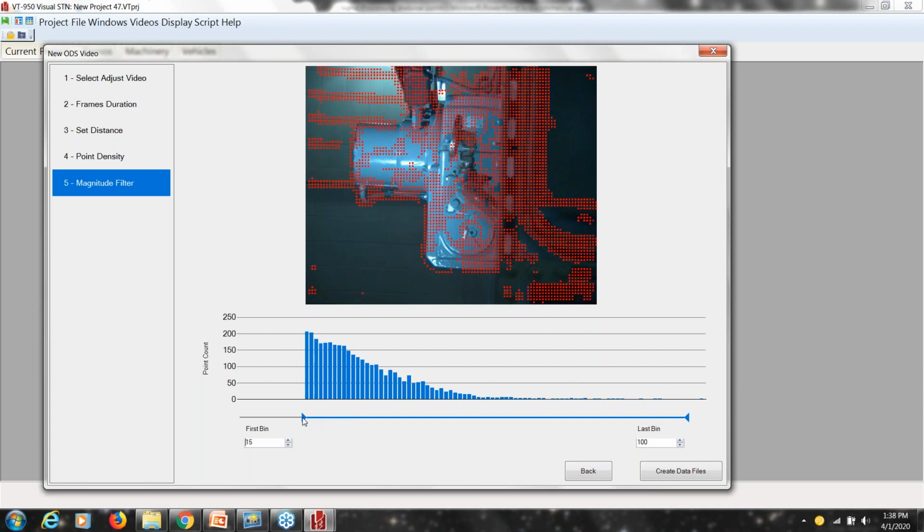Here is about right. A couple of the rules of thumb. This is your proximity probe housing, so I have that fully covered. I'm covering this bearing housing cover all the way around the bearing itself, and I'm going to get some good data from this. Since the camera is moving, I'm going to have to manually remove some of these remnants in here. As far as the high end, the high large amplitude, but not many occurrences.